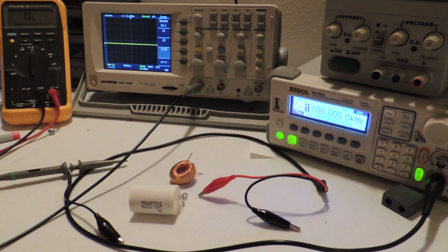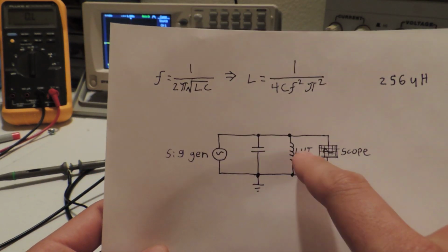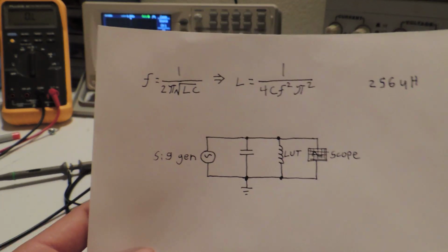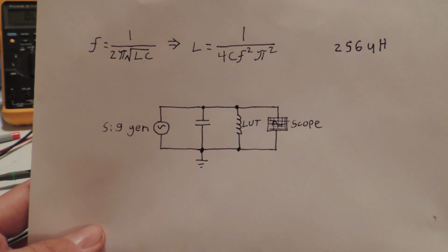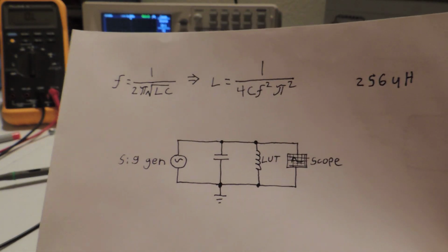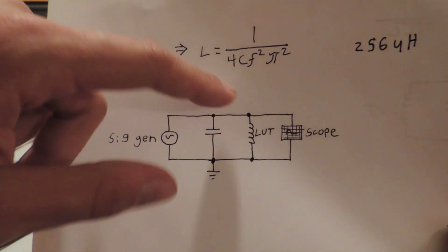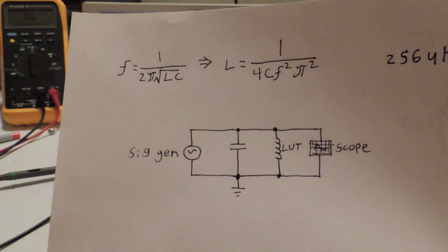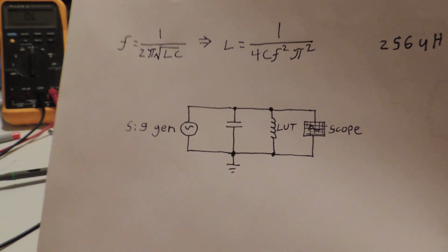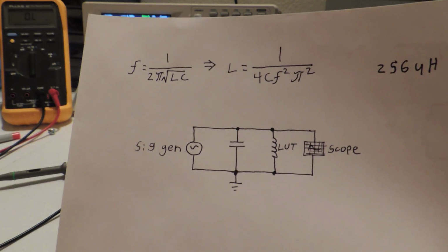So, a little bit about the theory behind this technique. I'm sure many of you are familiar with the basic LC circuit. This particular circuit that we're using is the parallel LC circuit. The thing about this that is rather novel, and what allows us to measure the inductance of an unknown inductor, is that the impedance of this network, basically the AC resistance from this point to ground, is at infinity, or incredibly high, like an open circuit, when the signal is applied at resonance.